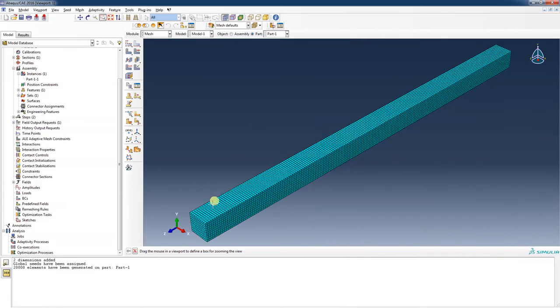If they were really stretched out, then we may have too coarse of a mesh, and we wouldn't be able to pick up the nodal locations and the deformation behavior as it gets excited by its natural frequencies. So that looks adequate.